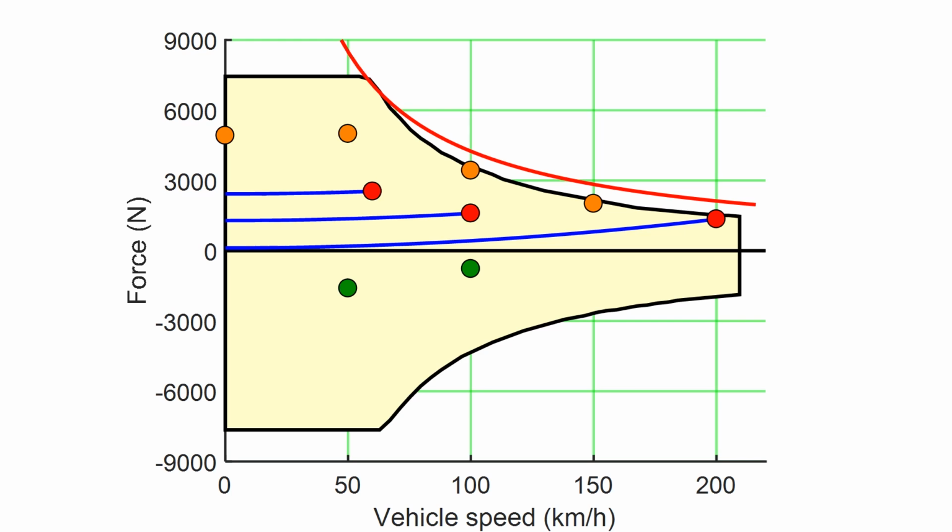We can see that the regeneration requirements are well inside the operating region of the electric powertrain and can be exceeded by roughly a factor of 4. A fully electric powertrain like this is able to regenerate at high negative forces, simply because the capacity to do so comes for free when we require such high positive force.